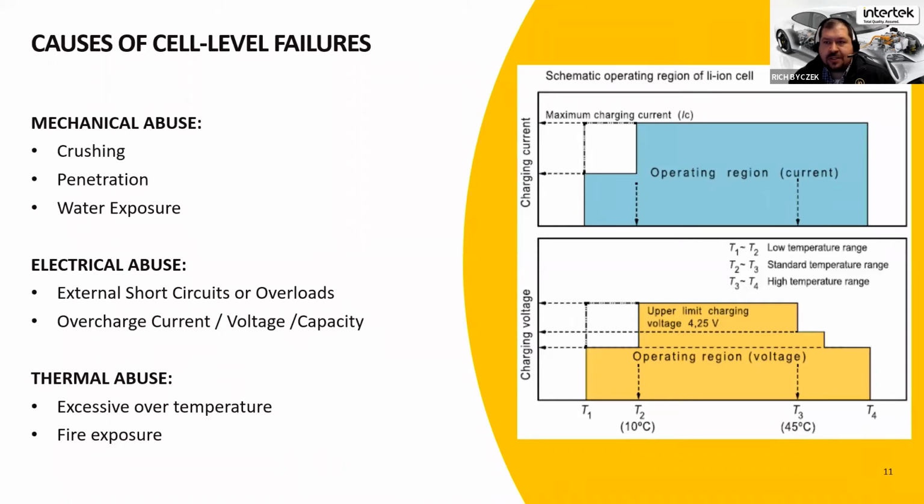An external short circuit could be a motor being seized within the vehicle. In an electric vehicle, for example, you're trying to drive current to push the motor to drive the vehicle. That motor becomes an essential short circuit load to the battery. And if you don't have the right protections in place, you're allowing an unsafe amount of current that's going to generate excessive heat. Could drive the battery below that 0% stated charge, but more likely it's the actual heating effect there that's going to drive the thermal runaway.